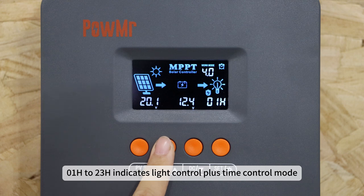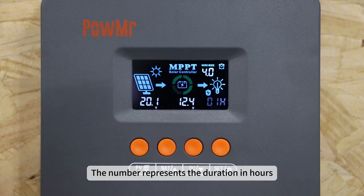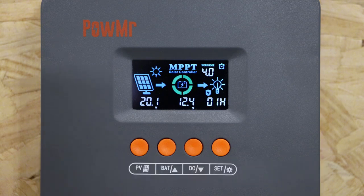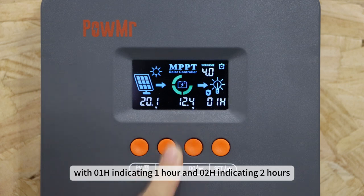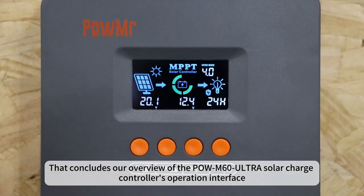01H to 23H indicates light control plus time control mode. In this mode, the controller will turn on the load output after sunset for a specific duration. The number represents the duration in hours, with 01H indicating 1 hour and 02H indicating 2 hours. That concludes our overview of the PowMr Ultra Solar Charge Controller's operation interface.